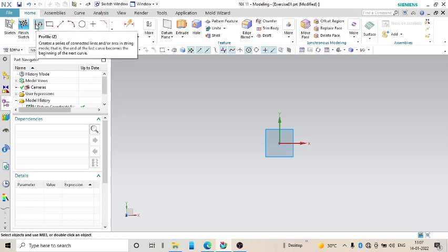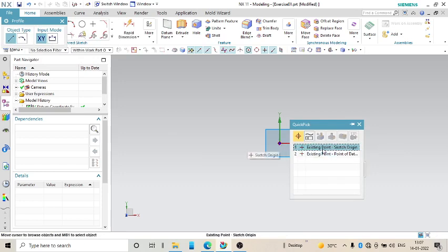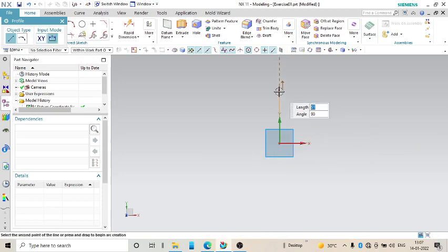using this you can make curved lines also. So you have to choose this carefully. So let us choose this particular option. Then you can click the origin point. You can see XC, YC 0, 0. Click there, existing point, sketch origin. Okay. Then draw some, you can see length 52 and angle 90 is already showing.